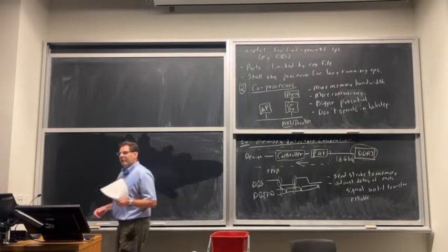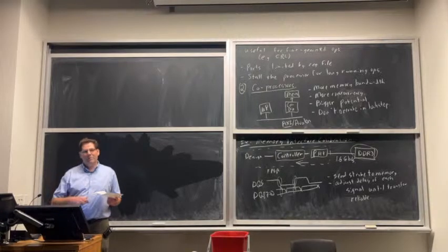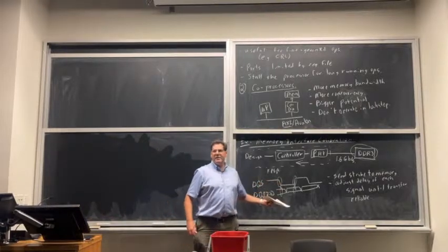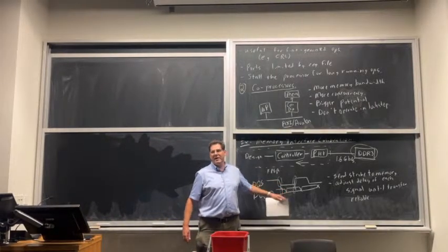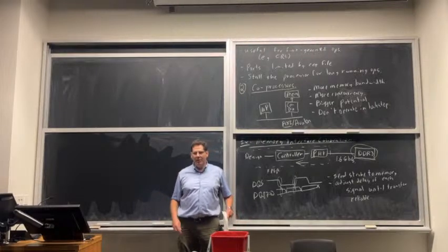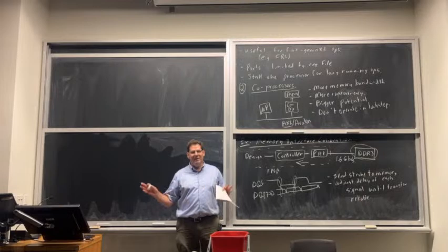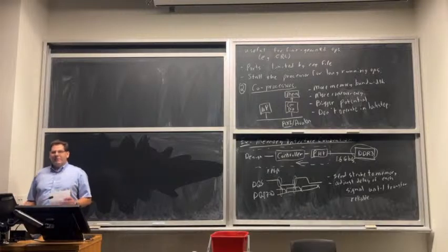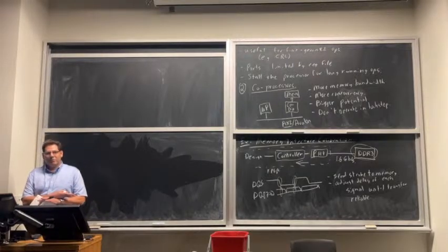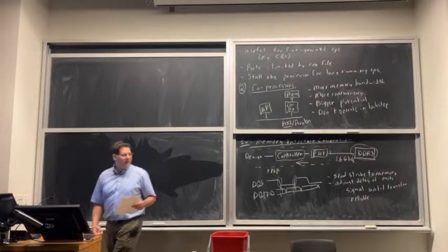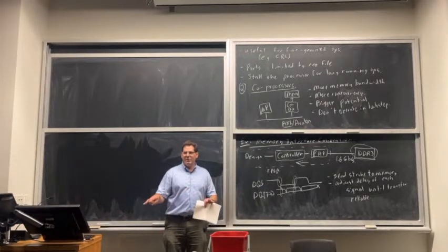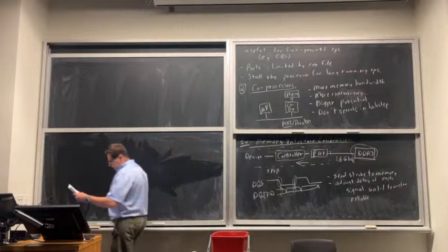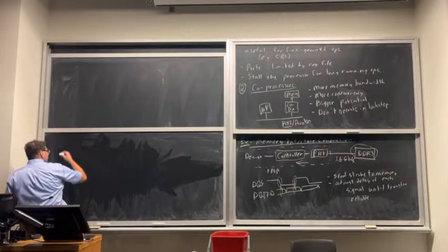So it's serial transfers. Okay, so serial transfers we'll talk about a little bit later on, but things like PCI Express, they basically don't have a strobe. They basically guarantee that you can recreate from the data a clock that you can use to sample. All right, and so which is even more tricky, which is why they take more area and they add more latency, but they get more bandwidth per pin. So if you're going to go a long way because your signal traces are expensive, they become the best choice at that point. For shorter traces where you can just have more wires and latency matters a lot, this is still the best choice, which is why memory uses it.